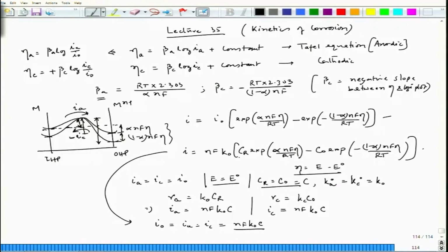So, then if I take this C out, then I am getting the same expression here, because this part is nothing but I0, isn't it? So, we are getting the same equation considering both the routes. One was considering the rate equation, and another one is the jump theory, that classical rate theory, where we are considering the jump of atoms due to the vibration of the atoms from one plane to another.